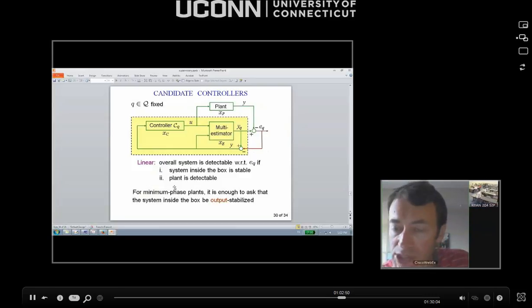Right. So I think it's the same as what people have used in adaptive control. It's indeed the output prediction error. You know both of these signals, right? You know Y and you know YQ. So sometimes people call it estimation error, which is a bit misleading because you're not estimating anything. It's indeed exactly the output prediction error. So you expect the error to go to 0. If it does, then it predicts or suggests that the index is correct. If it doesn't, then it falsifies the corresponding model and says that that cannot be the true plant. So yeah, this idea is, I would say, quite standard.